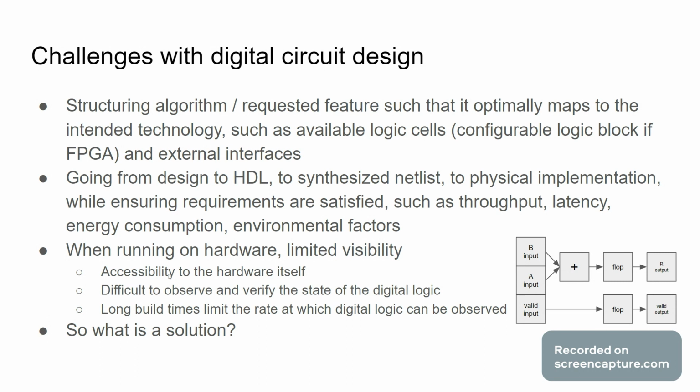And of course, once you're running on hardware, unlike a lot of microcontrollers or processors, you actually have very little visibility. I know this is highly dependent on the technology. If I'm not mistaken, I believe Microchip devices have ways where you can actually look at the registers as it's running. But I believe for the most part, if it's an Intel device, Altera or Xilinx, it's actually kind of difficult to see what's happening while your design is running. If you don't already have registers or an integrated logic analyzer in your design, you basically have zero visibility on what's happening while it's running.